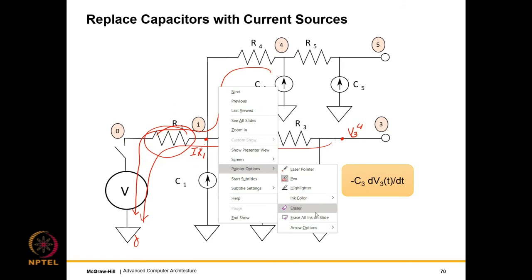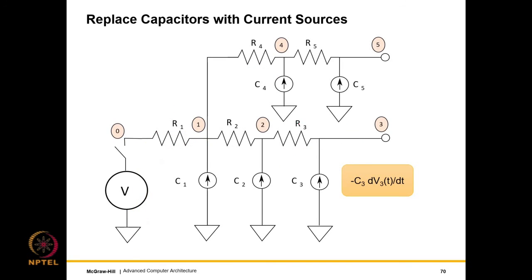Now let me consider one more example. Let us say I want to find the voltage over here because of the current source placed at terminal 2. In this case, the shared path will actually comprise these two resistors R1 and R2. So I will then say that Pij, which is P23, comprises these two resistors R1 and R2.